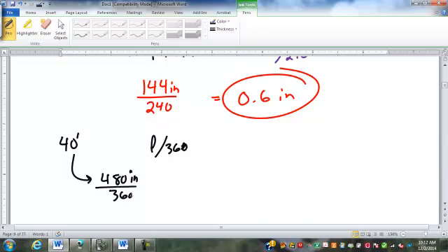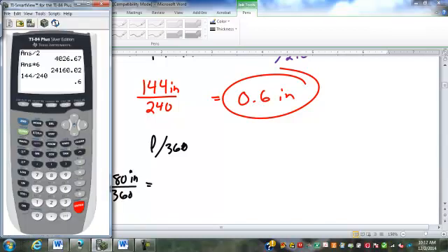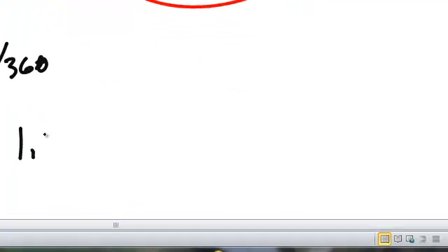Even if you take that over 360, you're going to get 1 1/3 inches. So it's almost 1 3/8 inch that beam can sag. Now you think about that, the problems that can cause, even though it's allowable, that would pass our analysis. But if you've got it moving an inch and 1/4 to an inch and 3/8,